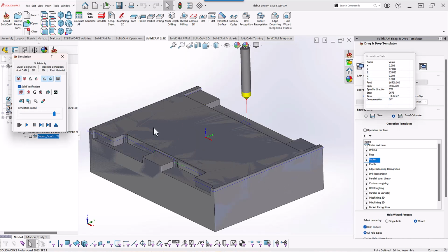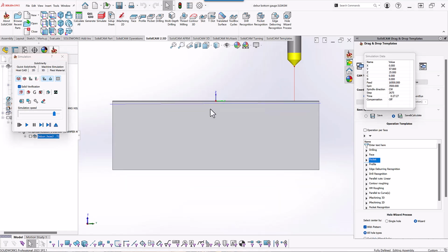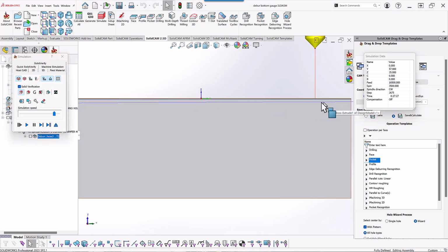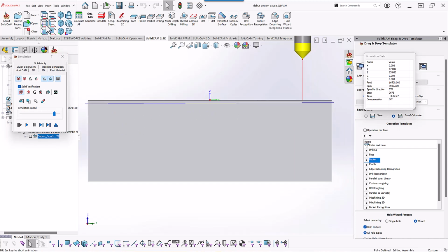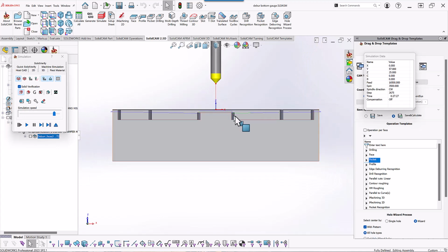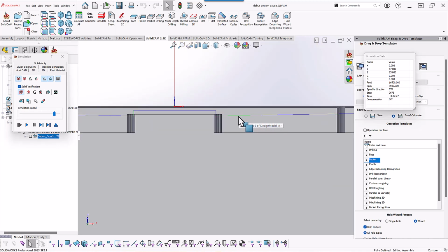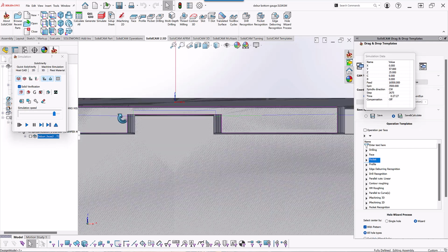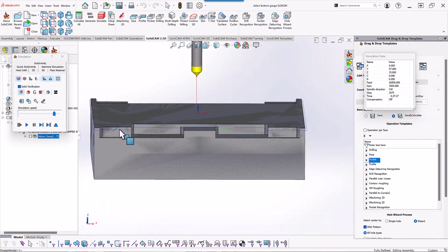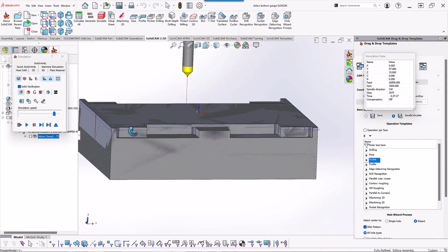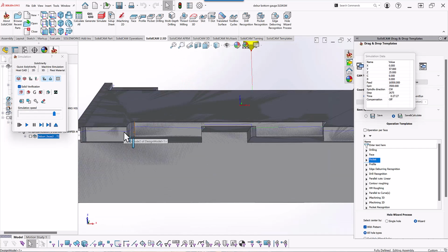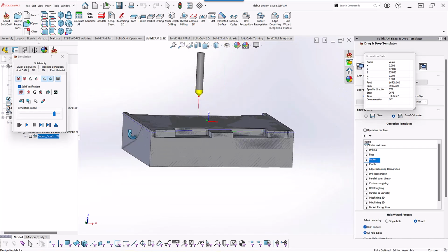If we take a look at the side view of the part, you can see that the tool path is gradually going further down. Looking at it from a different side, you can also see that it goes even further down over here. If it meets an area in the middle where it may actually gouge, it actually jumps back up to its minimum diameter, and then when it passes that area, it goes back down. Always creating the chamfer exactly the way it should be, and changing the diameter as it works around.